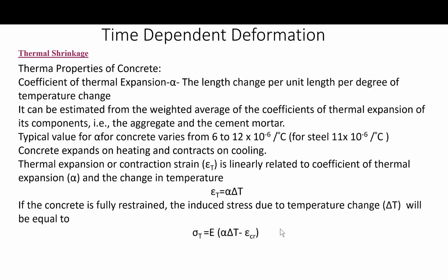Because sometimes, yes, you want to remove the forms and use them somewhere else and move on with the construction, but there are things you can do to make sure you dissipate the temperature rise without creating thermal shock to the concrete that will result in larger tensile stresses than the concrete's capacity at that point in time, like using insulation or whatever mitigation method is being done.